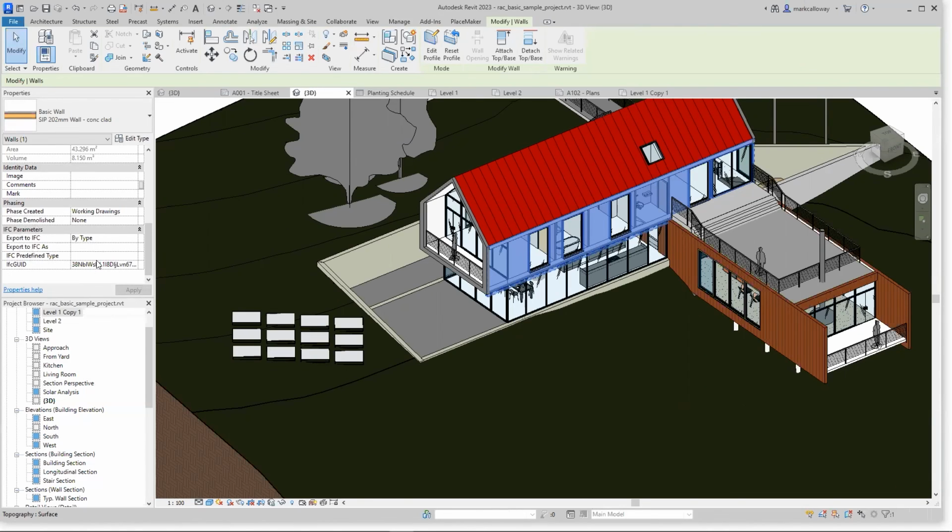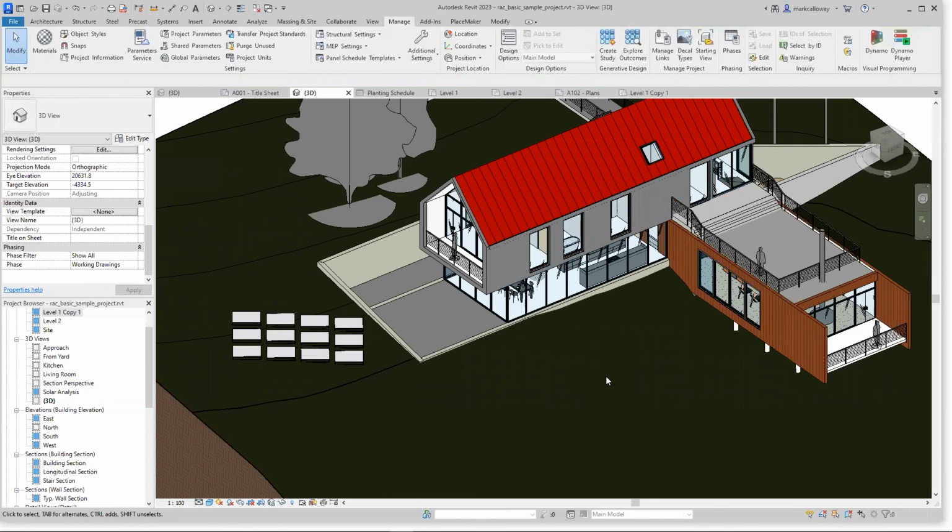And the second thing that I want to mention is the measure tool within Revit has also been updated as well. I just start the measure tool. In 3D views, it's now a lot easier to measure. We can pick faces, we can pick points, we can pick edges. I can left click one location, I can go across the model three-dimensionally diagonally to another point.